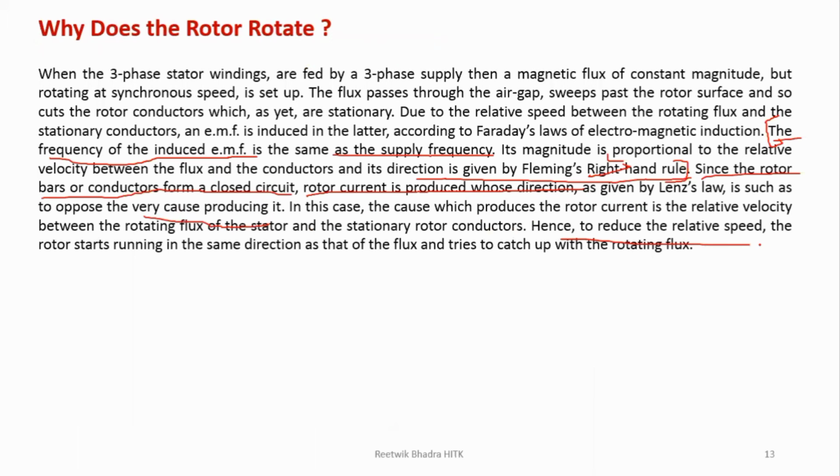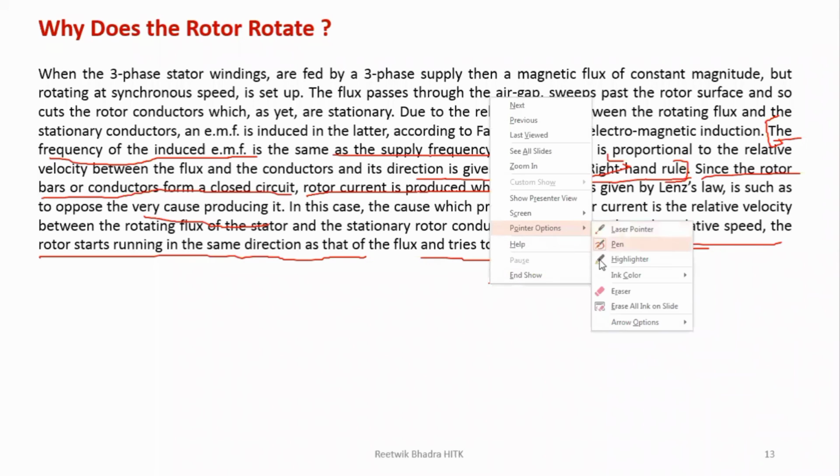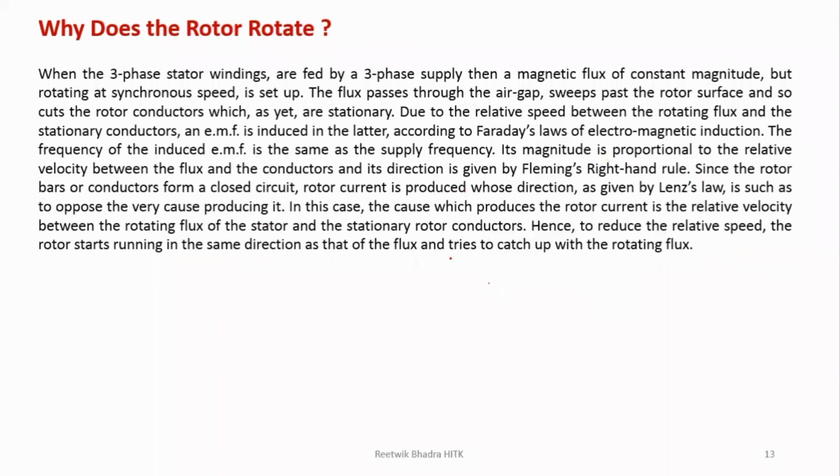You can go through this point. The rotor starts rotating in the same direction as that of the flux and tries to catch up with the rotating flux. It can never be at the same speed, because otherwise the relative velocity will be zero. So that's why this point is very important. It tries to catch up with the rotating flux. This is a small description I have given in my own words.